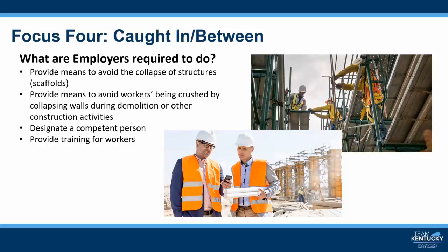During demolition, any standalone wall that is more than 1 story must have lateral bracing, unless the wall was designed to be standalone and is otherwise in a safe condition to be self-supporting. Jacks must have a firm foundation. If necessary, the base of a jack must be blocked or cribbed. After a load has been raised, it must be cribbed, blocked, or otherwise secured at once.